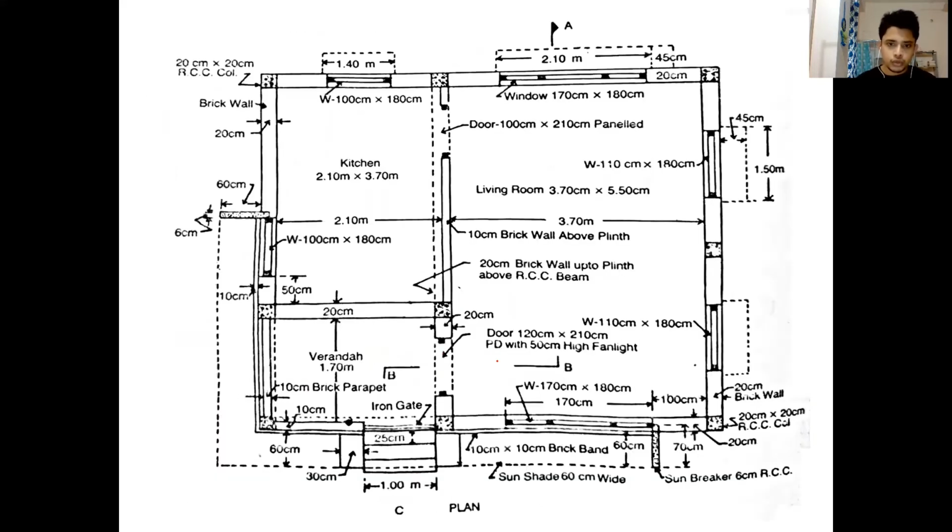Now this earth filling work will be done here, from the plinth beam to the plinth beam. The plinth beams are at the edges. Okay, the plinth beams are here, below the walls. So inside the plinth beam, we have to do earth filling work.